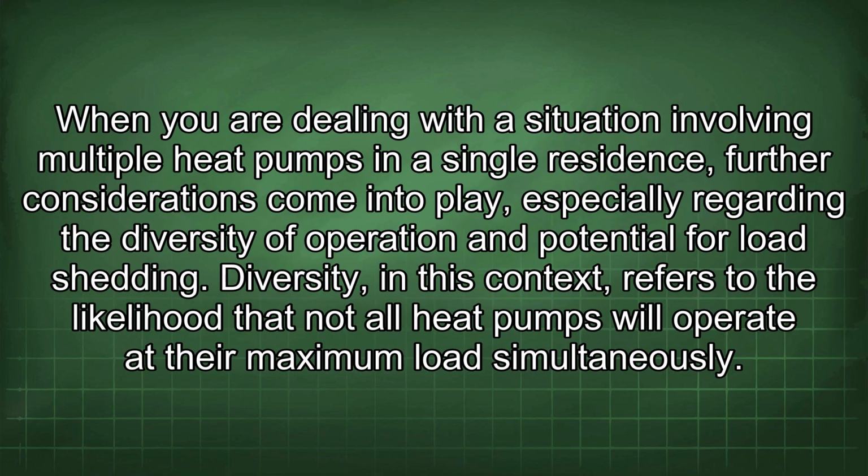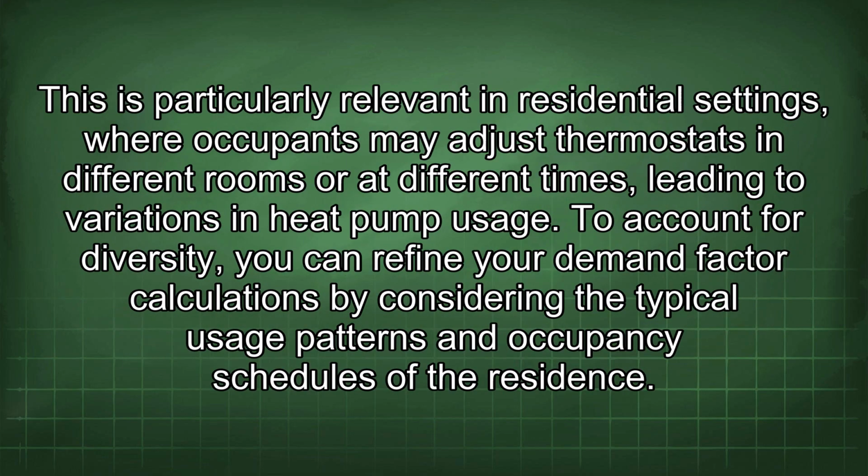When you are dealing with a situation involving multiple heat pumps in a single residence, further considerations come into play, especially regarding the diversity of operation and potential for load shedding. Diversity, in this context, refers to the likelihood that not all heat pumps will operate at their maximum load simultaneously. This is particularly relevant in residential settings, where occupants may adjust thermostats in different rooms or at different times, leading to variations in heat pump usage.